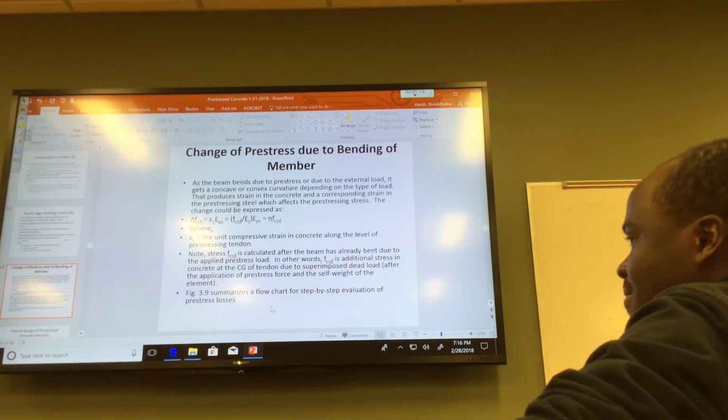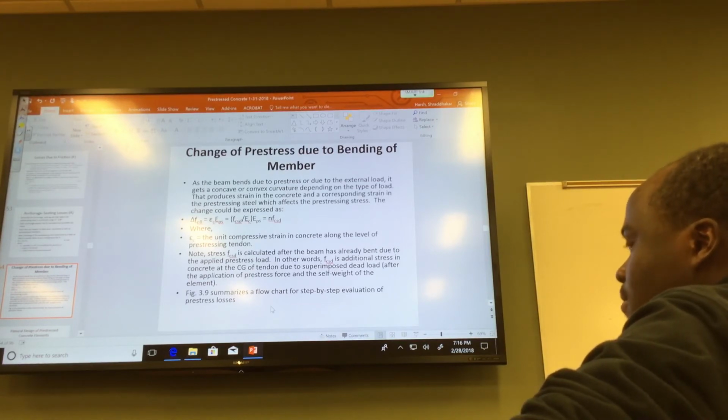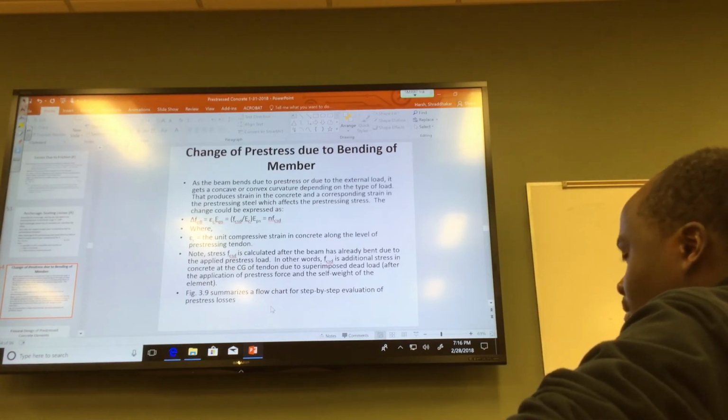Very good, excellent question, I have to tell you. Everybody gets confused. The word live and dead is not good, in my opinion. We should be calling them sustained load or transient load. Like, for example, wind is a transient load. It comes and goes in a matter of minutes or hours, maybe at the most. Earthquake load is hopefully in matter of minutes, right? You don't want to have more than minutes, right? So it is also a transient load.